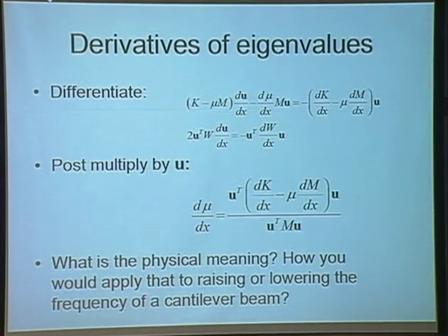They are cheap, and even if you don't calculate them, just by looking at the structure, you can tell how to change it in order to change the frequencies most efficiently. So you completely satisfy the Coiter paradigm. Before you calculate the derivative, you know which derivatives are going to be large and which are going to be small.